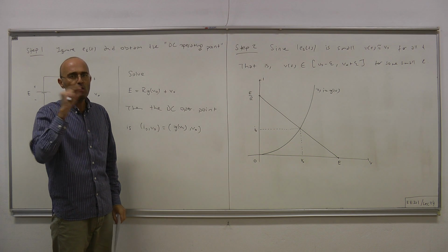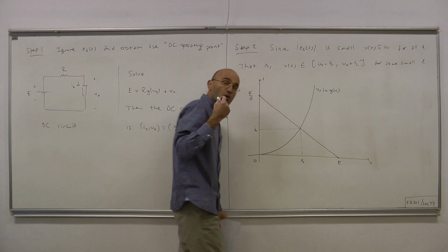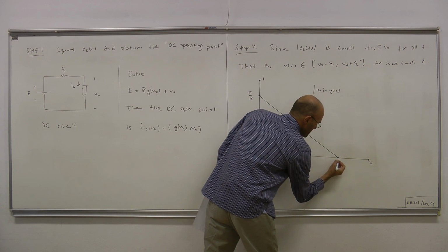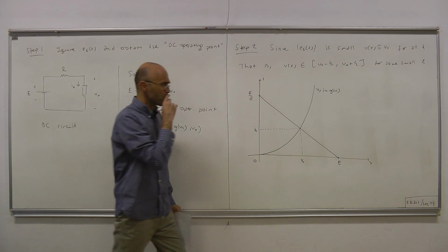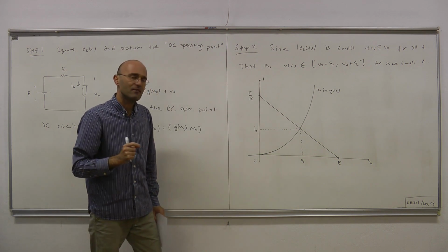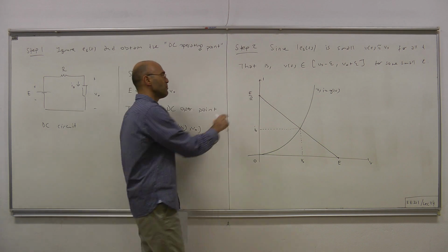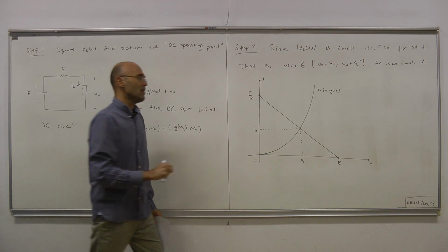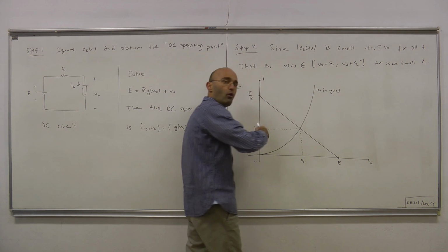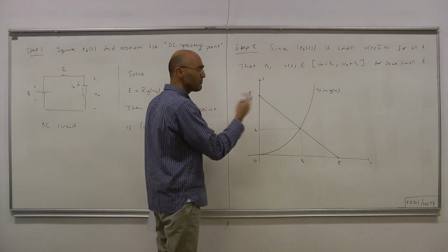Now ES of t is small, therefore this load line will be, depending on the value of ES of t, such that the point that intersects the horizontal axis will be fluctuating around E. Now, since the slope of this load line is determined by R only, that fluctuation would mean that this load line will move back and forth, remaining parallel to itself at all times.